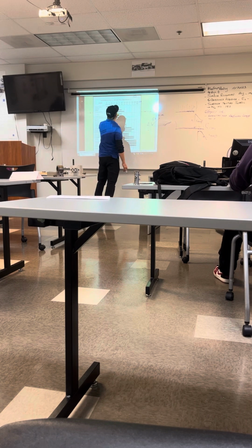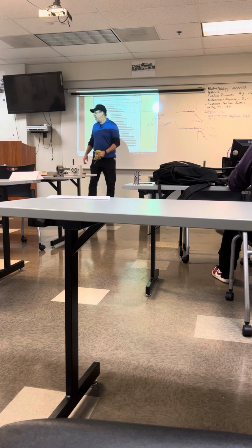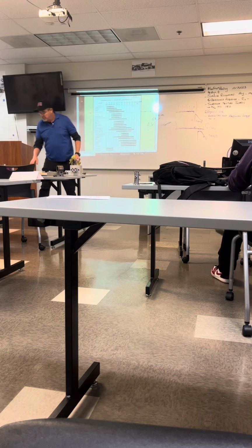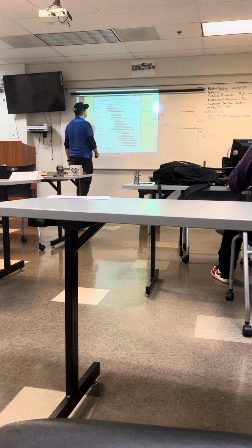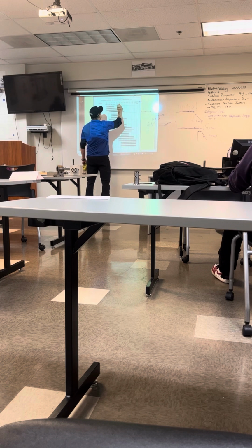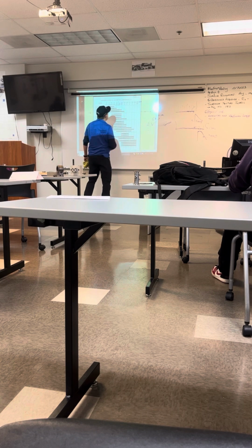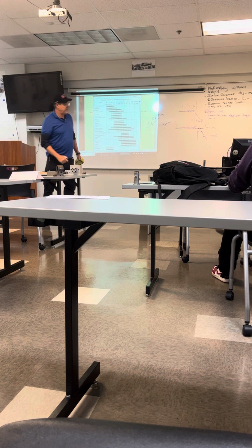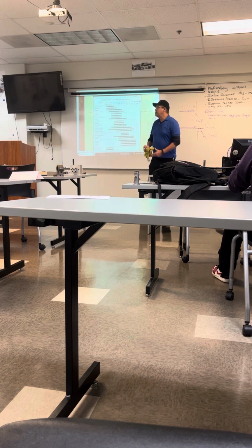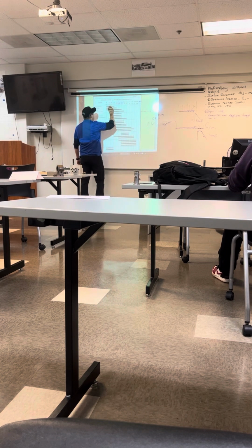And then commonly what we do. I don't see that in my book, let me see. Yes. And then 63 is equivalent to 1.6 micron, 63 millionths of an inch. 32 is equivalent to 0.8 micron. Yeah, 0.8. And as you notice, this is the average process that obtains that kind of surface roughness.